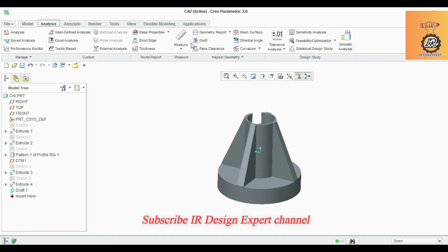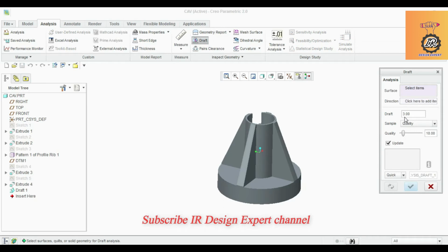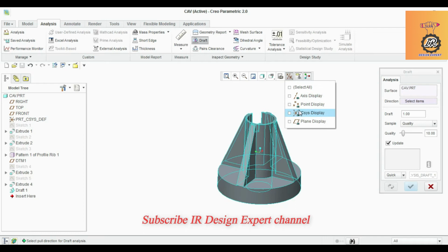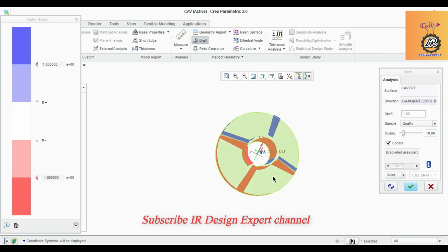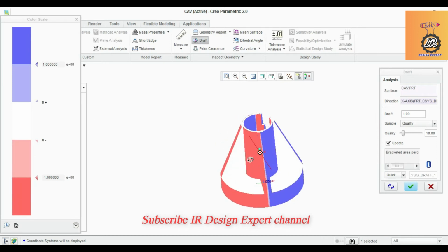Now going to analysis, the draft analysis. So 1 mm will give, then only we see the entire details. You can select the coordinate. Okay, now it is created.